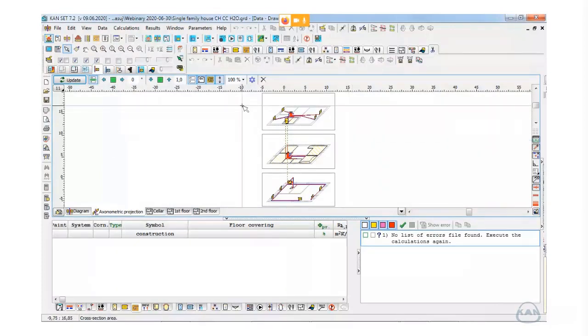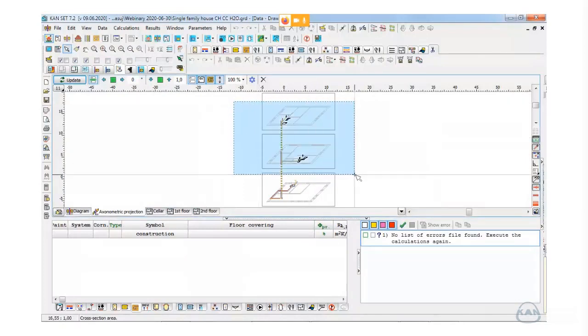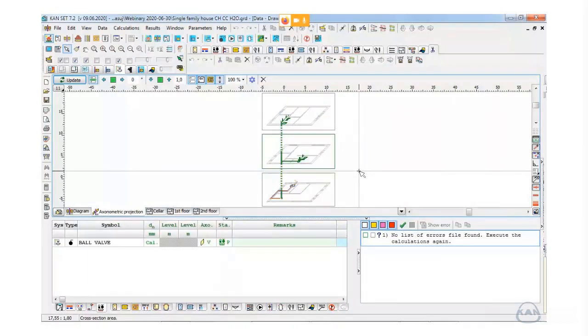Now, if I select, I would select only the elements of the system, but let's choose, for example, cooling, and then water supply. So depending on which mode I am choosing, I would select the elements. And now, for example, I would like to select the elements of the water supply system, but only from 2 stories. So with axonometry, I can do that.